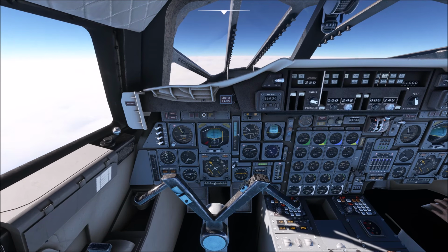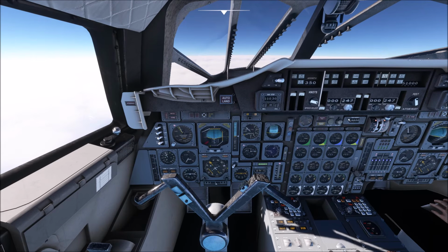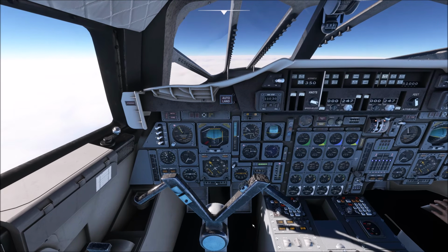When you do eventually go through 50,000 feet, max climb will go to max cruise, and it does it automatically, and it will then just attempt to maintain that same kind of balance while gradually increasing height as the fuel weight comes down. Okay, I hope that's been helpful.